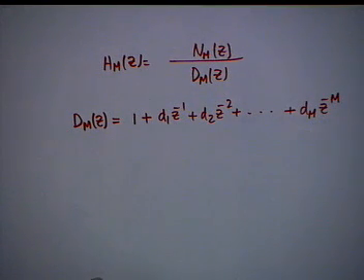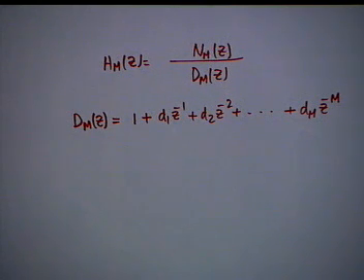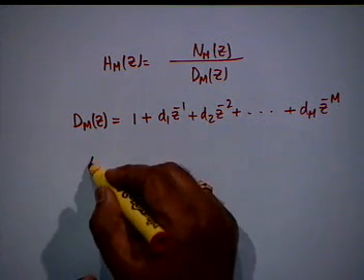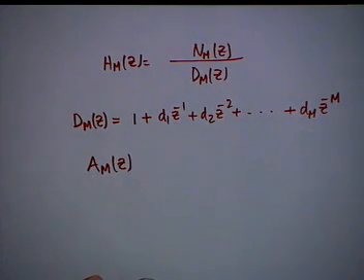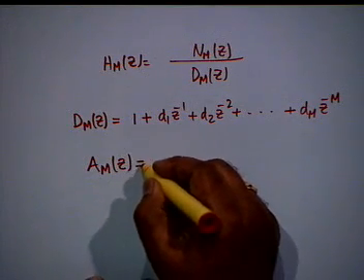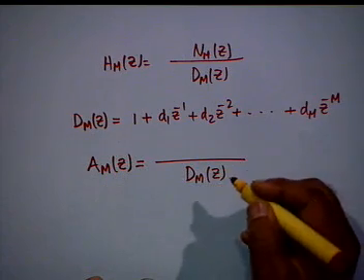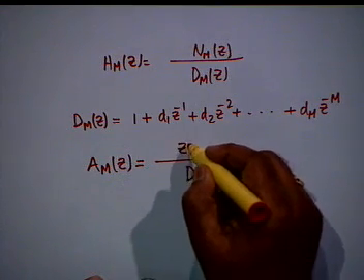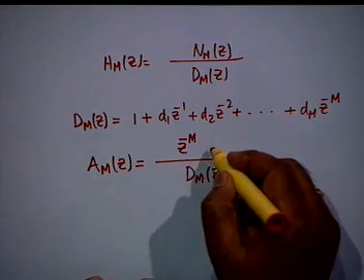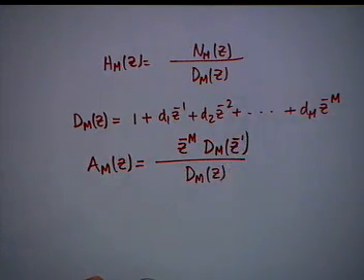All right. Instead of finding the roots, we go via media of an all pass function. In other words, the first step, we construct from this an all pass function with the same denominator D_m(z), and the numerator therefore shall be z to the minus m D_m(z inverse).